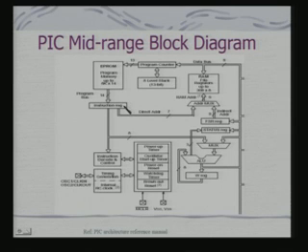This is your instruction register. Its basic job is to take the instruction whose address is provided by the program counter. This instruction is decoded by this block to generate what is called the control and timing signals for the internal blocks of the PIC processor.